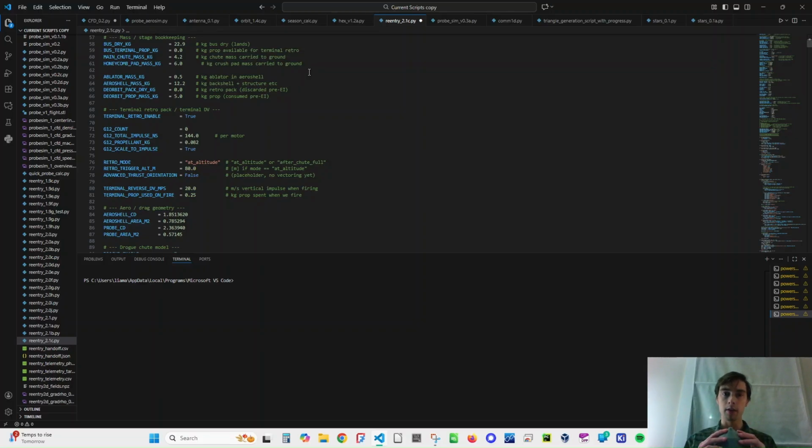And because we have the fourth thruster array, we can make it so it doesn't actually control our orientation at all. Even if two fail, we still have two in pairs. That's how they're fed. So yeah, bus dry. That is the mass of this. This is 20. It's less than that really. It's more like 21 kilograms.